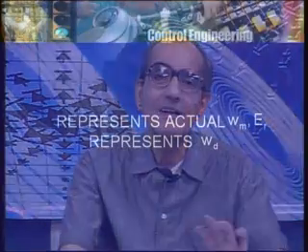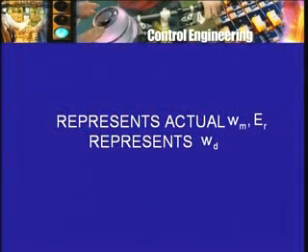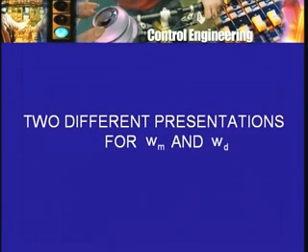We use one representation for the desired value and we get one representation of the actual value, so that there is a non-zero difference between the two when the conditions are the desired ones, which produces a non-zero voltage which causes the motor to run at the correct speed.